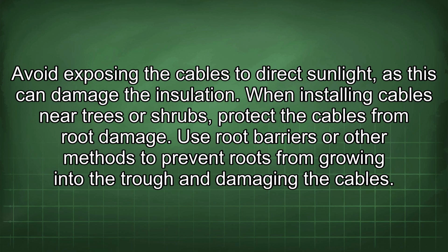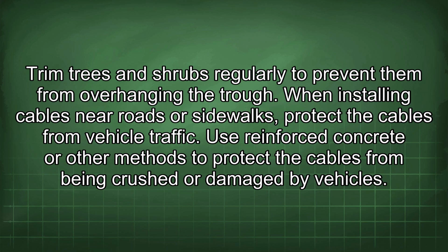When installing cables near trees or shrubs, protect the cables from root damage. Use root barriers or other methods to prevent roots from growing into the trough and damaging the cables. Trim trees and shrubs regularly to prevent them from overhanging the trough.